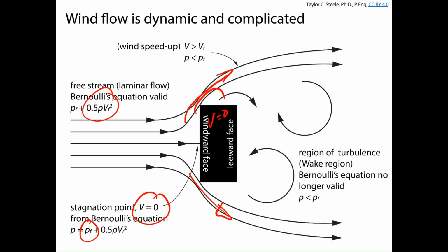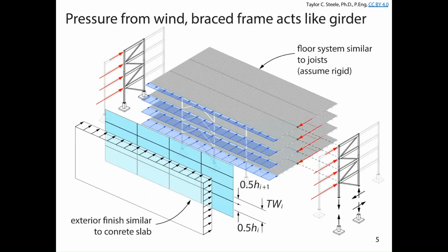Okay, basically what happens to the structure more or less, as it gets taller, as the wind blows at it, the wind's going to push the structure, but these vortices are also going to cause it to twist and sometimes move side to side, and this can be a very complicated problem. If we're dealing with structures that are short and stiff enough, we can more or less treat these kinds of pressures and fluid flows acting on our structure as an equivalent static uniform pressure.